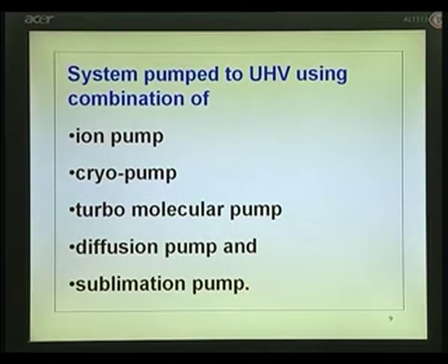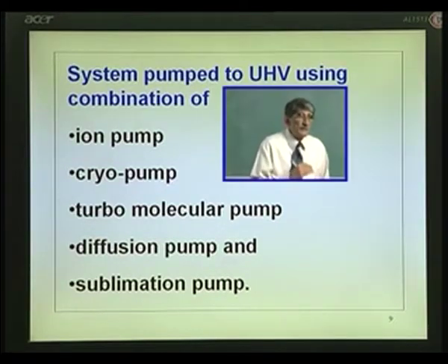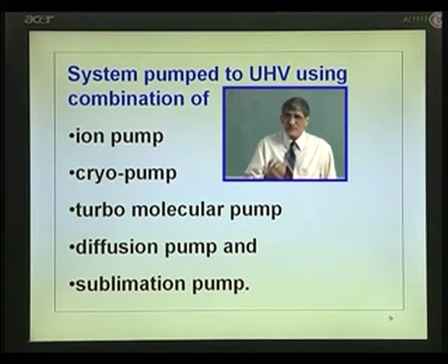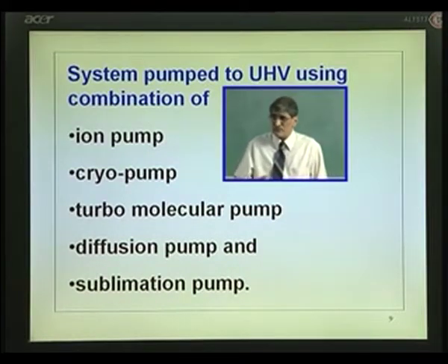Now, this high vacuum in the chamber is obtained by using pumps which are oil free. If it is a pump which depends upon some oil system, then there is a fear that oil may get into the chamber. In fact, in the conventional vacuum coating systems also, you have to be concerned about it. The best thing, of course, is to use turbomolecular pumps, which do not use oil.